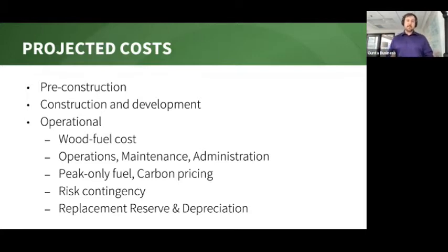So when we design projects, and I'm in the business planning stages, we always look at the current intact heating system, and we always anticipate using it to a very small level to just manage the peak loads. So in effect, newer systems, they're not getting creosote buildup. In many cases, we're not ever recommending a single biomass boiler for a district heating load.